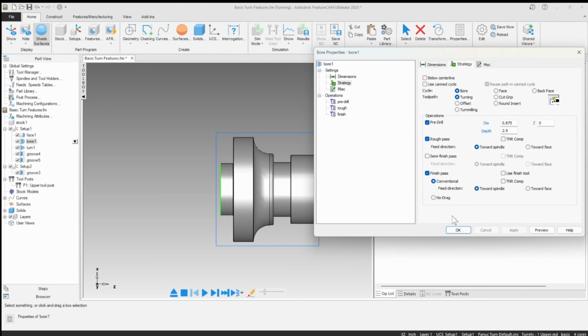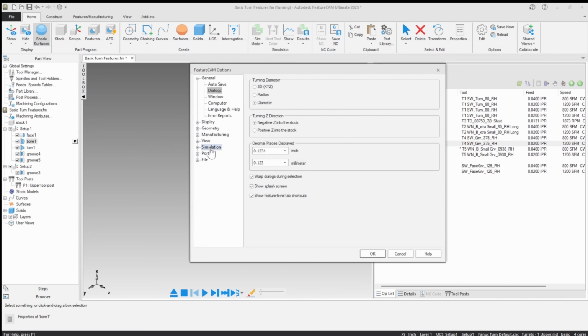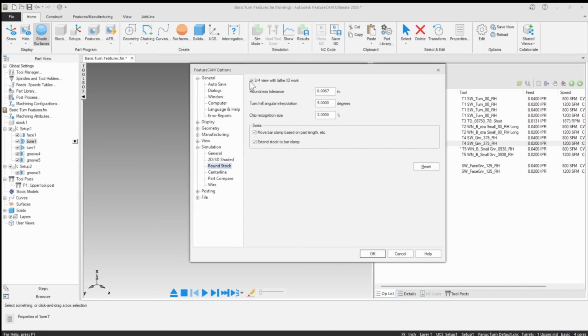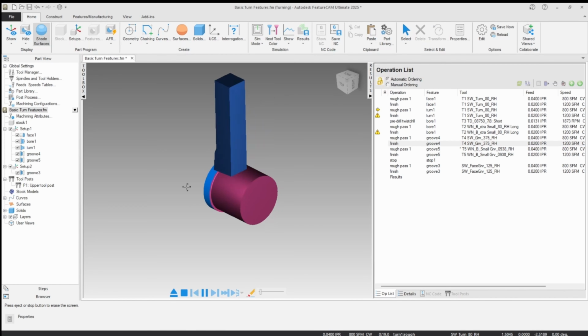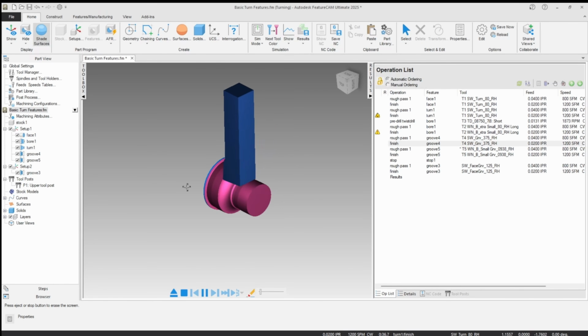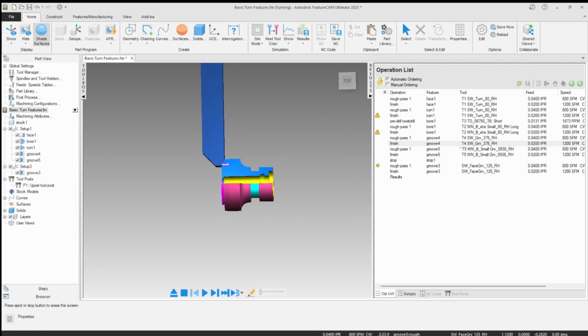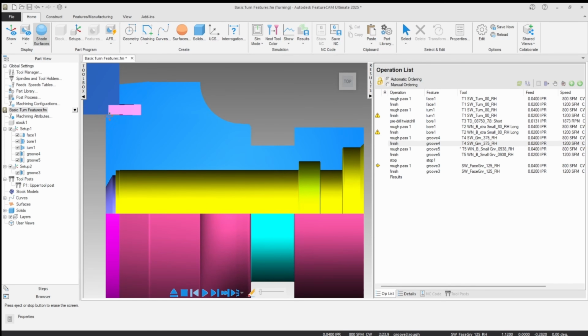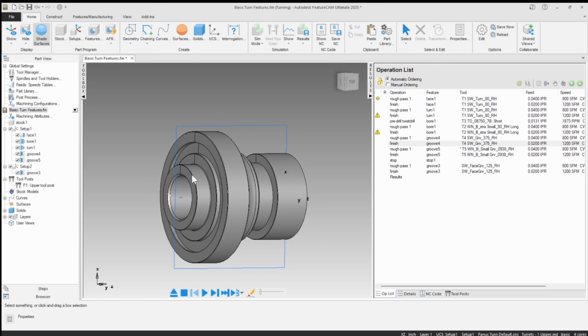Now we've got the rough pass and the finish pass. Now, in my simulation, I have that 3/4 view, just as a reminder. In the simulation and round stock, I've got 3/4 view with lathe ID work on. So now we're going to run this, and as soon as we hit the internal work and we don't have a crash, and you see it's sectioned out, there's our drilling, so on and so forth. So if we look at some of the settings that we have, it looks like I have a gouge here. That's the feature I had left in here before starting the video that's doing that groove. Well, I have to finish turning this.